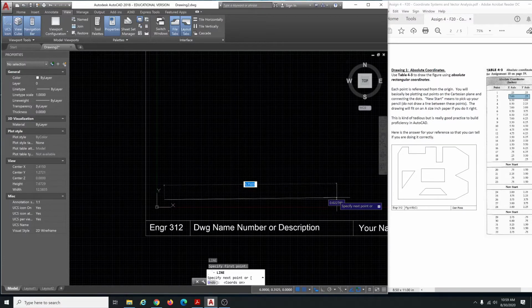So I'm going to find point 7, 0.25, which is over yonder somewhere. There it is. I don't want to move the mouse, but look down at the bottom of the window in the coordinates. You see 7, 0.25, right? So that's absolute 7, 0.25. That's what we want. We don't want to use the numbers that are on the line command. Those are relative. Okay? So click that.